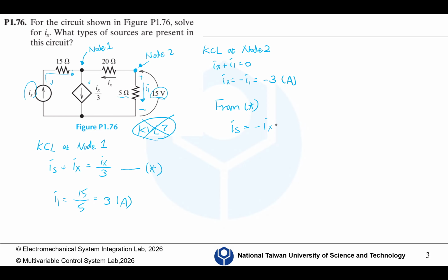Then we can write positive 10 I3, plus 20 I3 because we have converted 2Vx to 20 I3, and then plus 6 times I3 minus I1 equals 0. Okay, double check. Yeah, it should be correct.